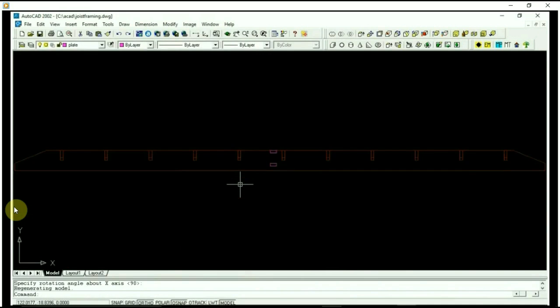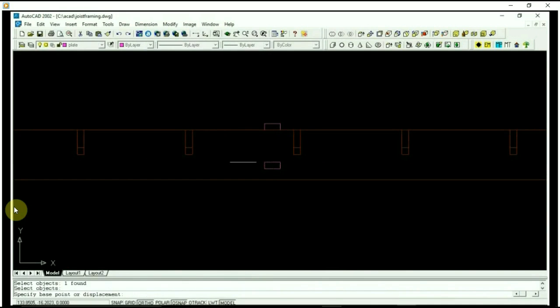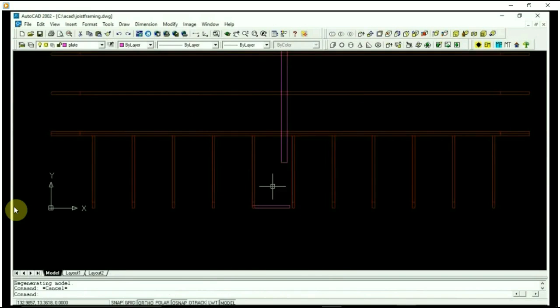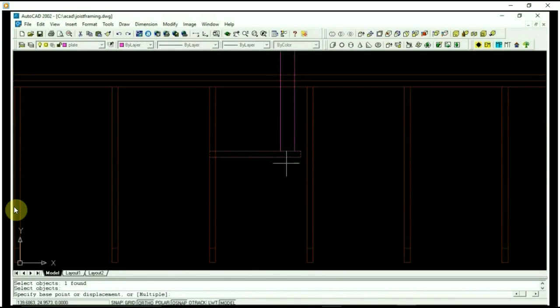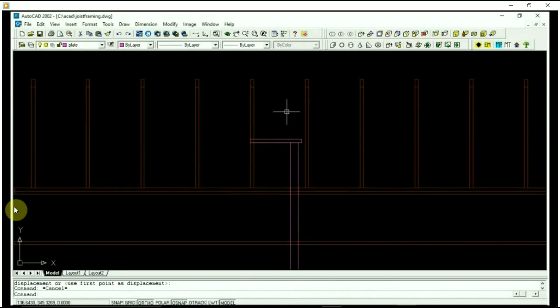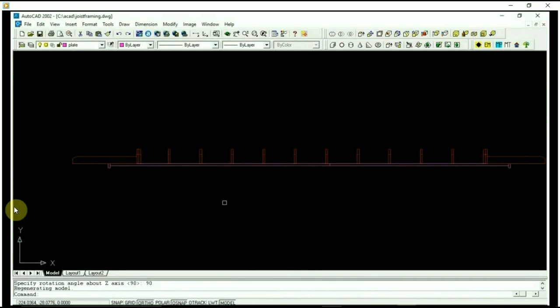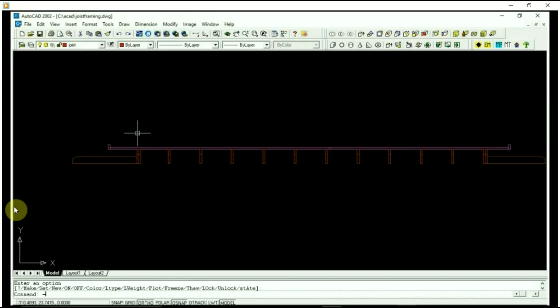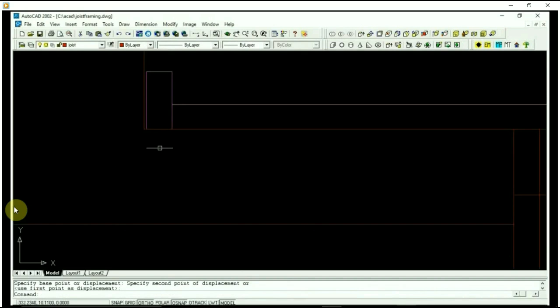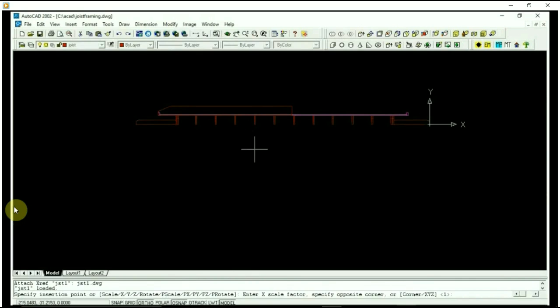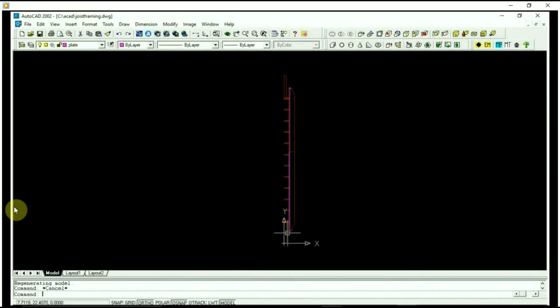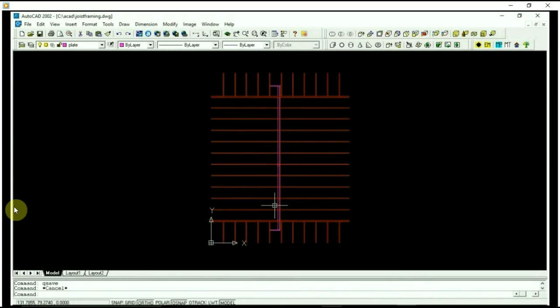That process took, I would say, maybe 30 to 40 seconds per drawing. I know we had one job, and I ended up writing a program so that I could do the PDFs automatically. There's something called Inventor Apprentice. It uses Excel, so if you use Excel, it'll speak to Inventor and change things like iProperties, and you can print a PDF through Inventor Apprentice. That's where I initially wrote the program, and it allowed me to print the drawings off.